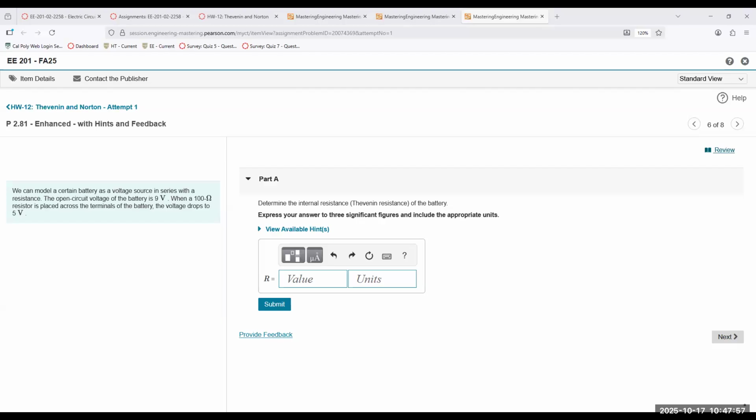So for the lab, you're going to build a circuit. You'll have the circuit and you have these output terminals. Let's call them A and B. A and B is where we are calculating or measuring everything, right? So the Thevenin voltage is measured at A and B. The current is also measured at A and B. The resistance is also measured at A and B, right? So you take your meter's two terminals and you connect it directly to A and B.